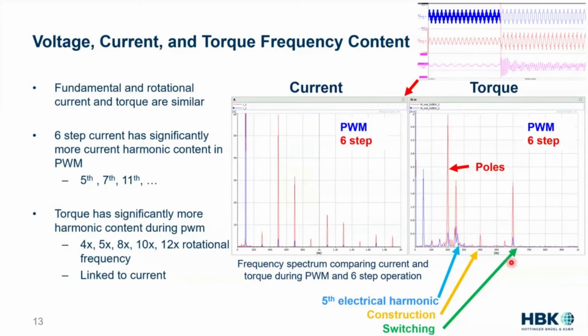And if we remember, I said that the torque follows the envelope of the ripple, or the envelope of the peak current. That's what this is. That's 6-step operation, 100 hertz, 600 hertz switching. We get this big peak out at 600 hertz. So this is pretty wild that we get these huge influences on torque from the excitation, and this is really attributed to that torque ripple. And again, this is all going to be resonated out into noise and vibration at some level.